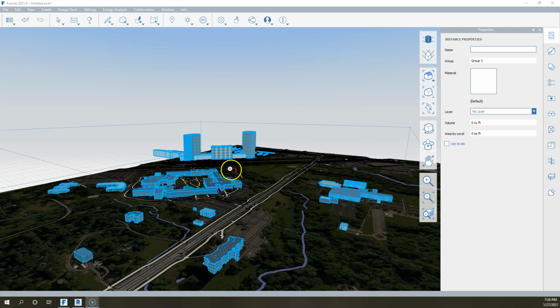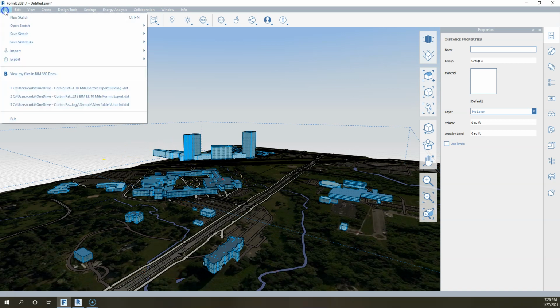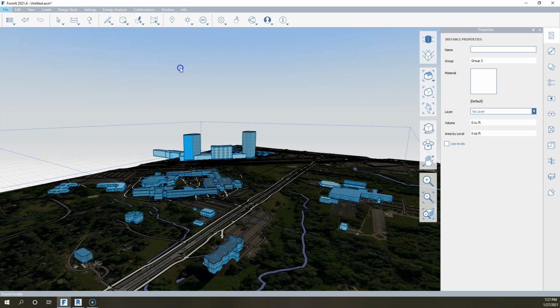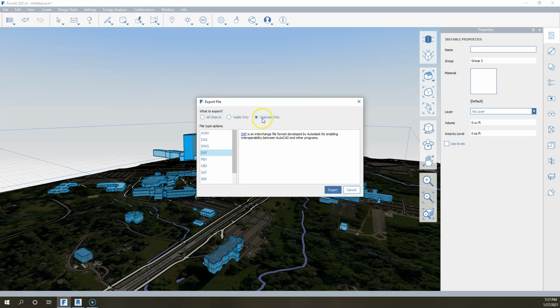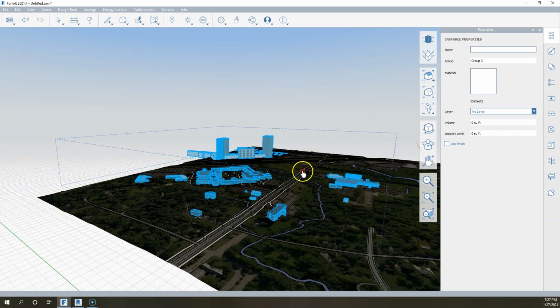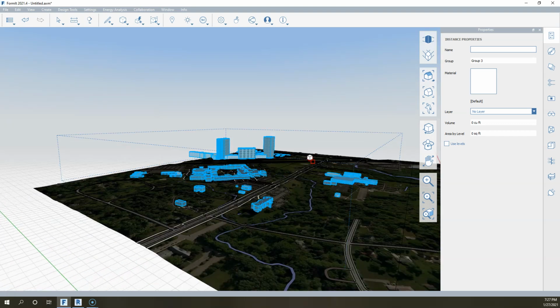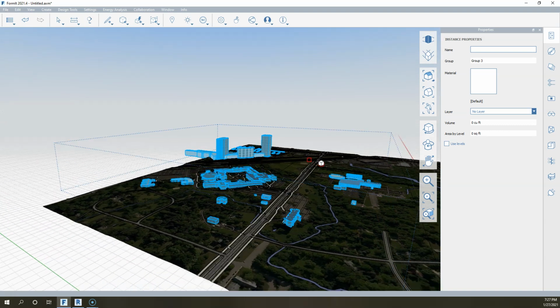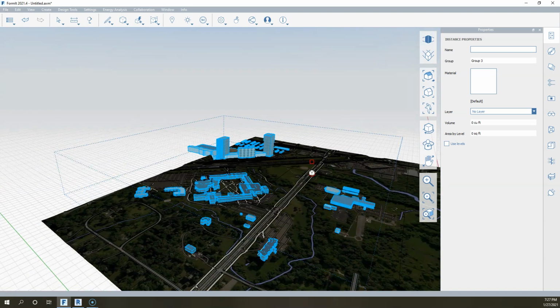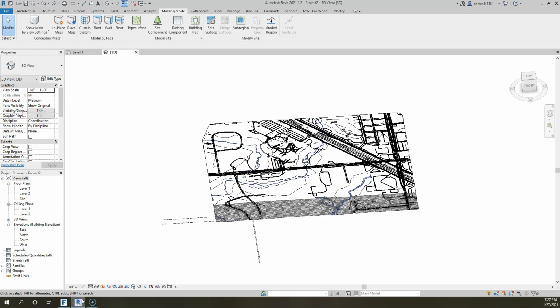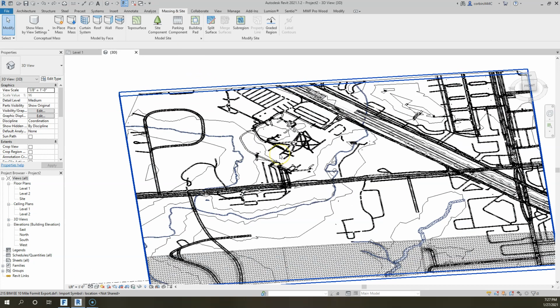So I just want to show you, I went to File, Import, imported our building file, and then I left it selected, and I went to Export Locally, and I actually went to Selection Only and made sure my building was selected. So I exported that building like that. And the reason why I brought this back on sooner is that I'm going to do one extra little step here before we bring it into here.